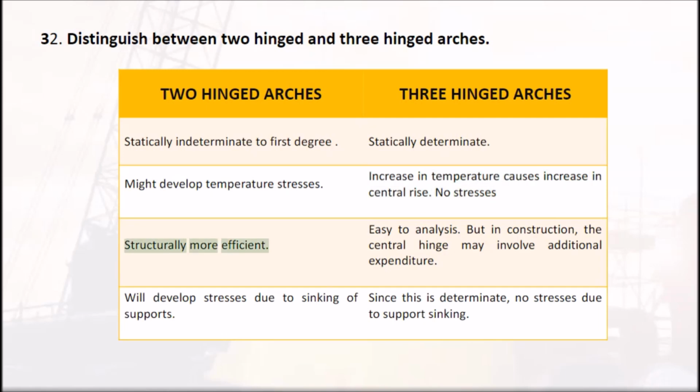Structurally more efficient. Will develop stresses due to sinking of supports. 3-hinged arches: statically determinate. No stresses. Easy to analyze, but in construction the central hinge may involve additional expenditure. Since it is determinate, no stresses due to support sinking.